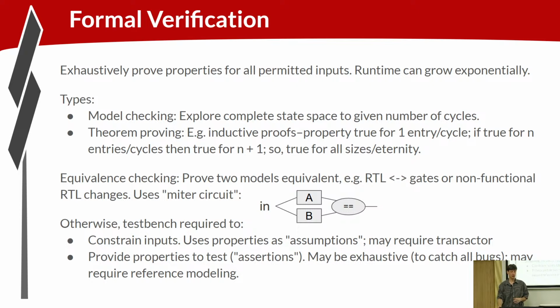Formal verification, whether it's model checking or theorem proving, tends to work to a certain scale and then explode. The nature of state spaces is that the more bits of state your model has, the more states you can enter, and it's explosive, right? If you have one more bit, you have 2x the number of states. So exponentially, your model grows in complexity and the formal verification effort grows. So you tend to reach a certain scale and then formal verification becomes infeasible.